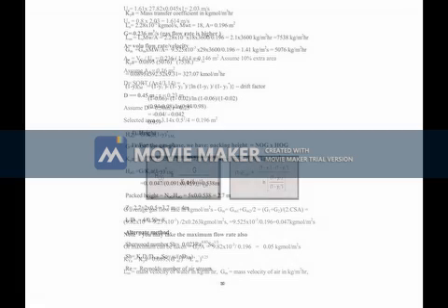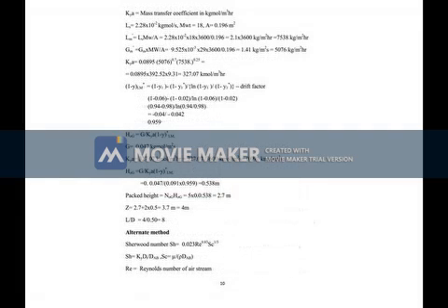So now you have to find almost every flow. Gs is there, so G2 can be found out. What is Gs? Gs is equal to G2 into (1 minus y2), or G2 is equal to Gs by (1 minus y2). So G1, G2, Gs, L1, L2, everything is known.